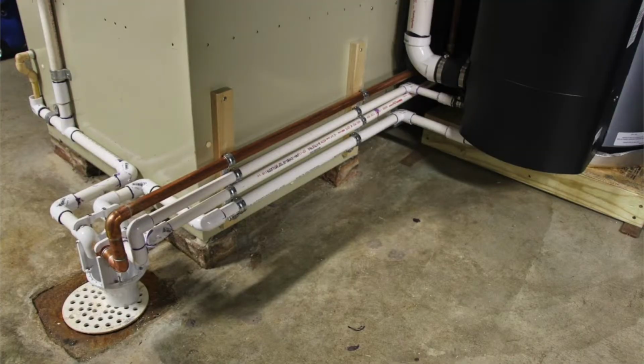All right, number 1, an air gap. The air gap between the public water system and any system that could cause backflow is the best method for preventing backflow. Essentially, air gap meaning there is no solid connection between point of use and the city. It can't siphon back up because there's no connection there.